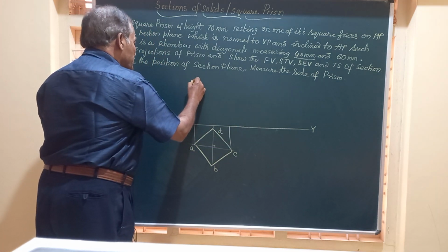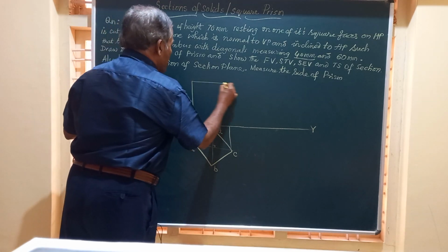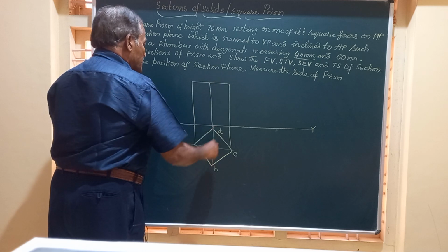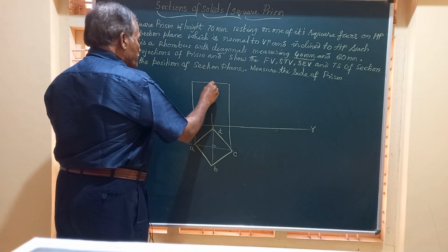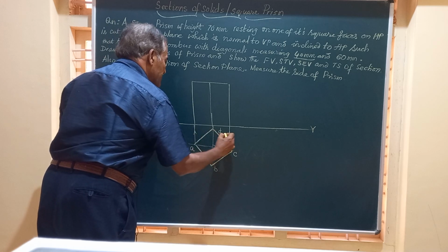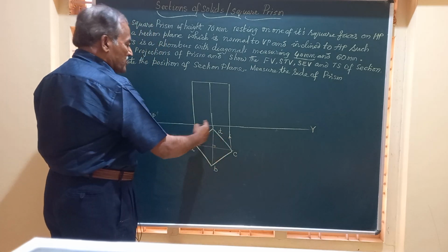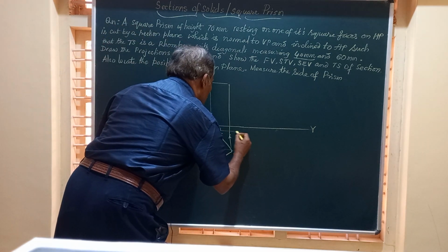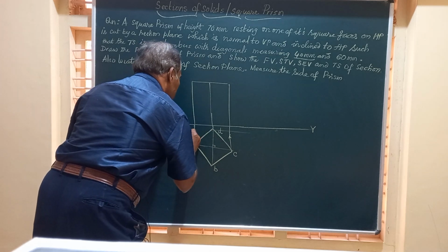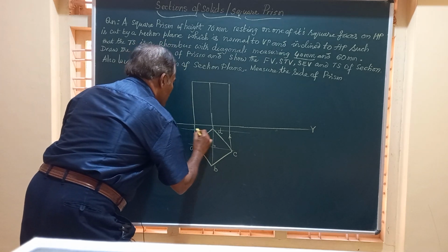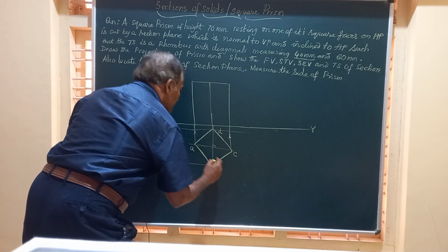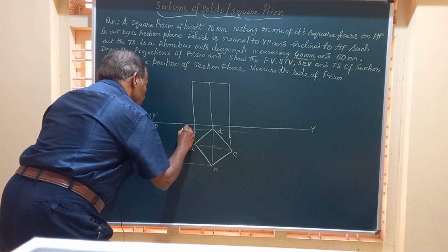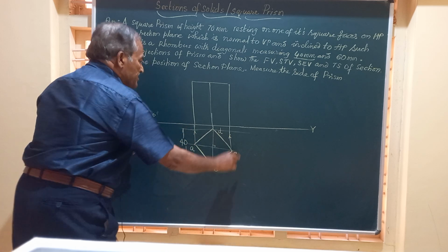So friends, front view is going to be a rectangle, and we will have this line here. So all these lines are obtained by projecting from the top view. So just an arrow like this, that means we have to construct this figure and obtain this. And according to this it is going to be 40, or I can show this side also. Any one side, we can show this dimension BD is equal to 40 millimeter, and we have named this as A, B, C, D.